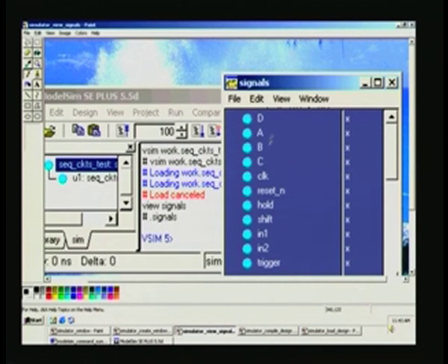And it also shows, right now, a don't care, that is X here, and it means we have not started running the simulator. When you run the simulator, you should get the waveforms. Because it was not run, we have just loaded the design, and it is showing don't cares because no valid data is available.